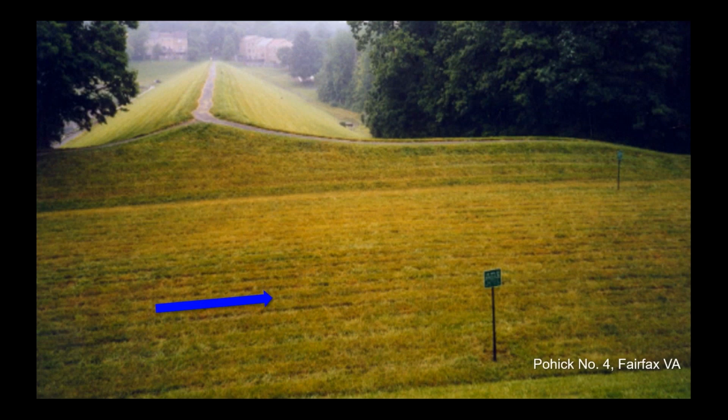Now, in some cases, really the ideal situation is if you can take the auxiliary spillway and provide a distance or a separation zone between the spillway and the embankment. That's ideal. But the topography of many dam sites just doesn't permit that. And in some cases, the spillway is located immediately adjacent to the embankment, like what you see here.